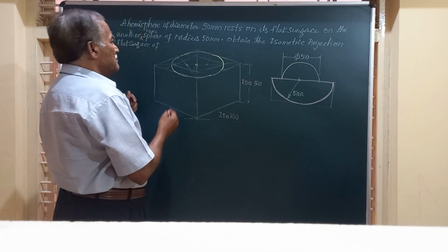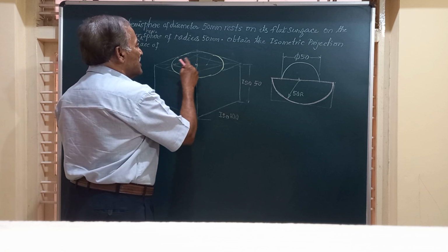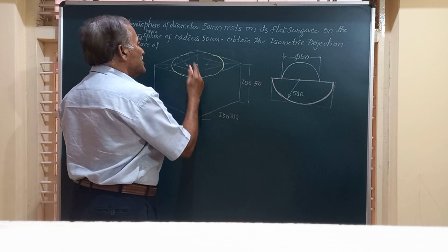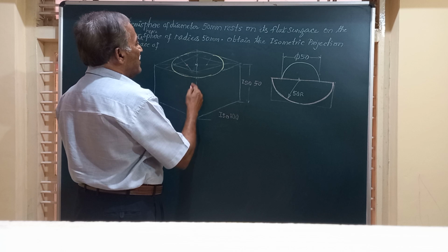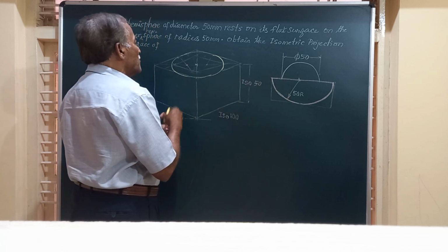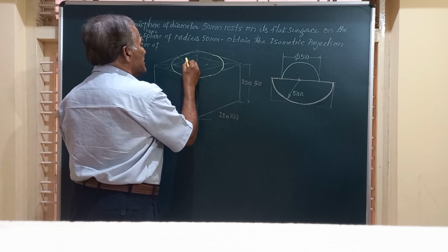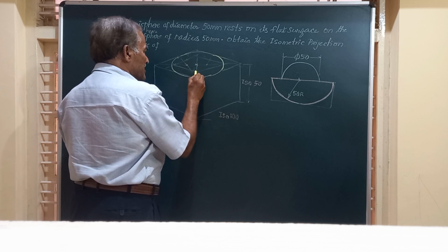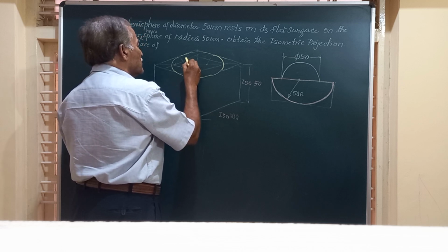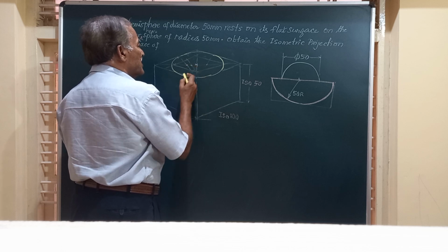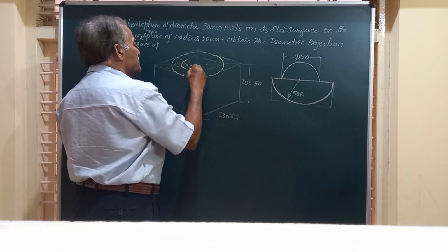So now friends, I follow the same procedure. For the smaller parallelogram here, using the four center method, we are going to have another smaller ellipse. How to obtain it, friend? I will take this as the center, the opposite center as the distance, take center C1, opposite side as the radius. You can obtain this point, center 1, for that. With center 1 and this as the distance, we can construct an ellipse here.